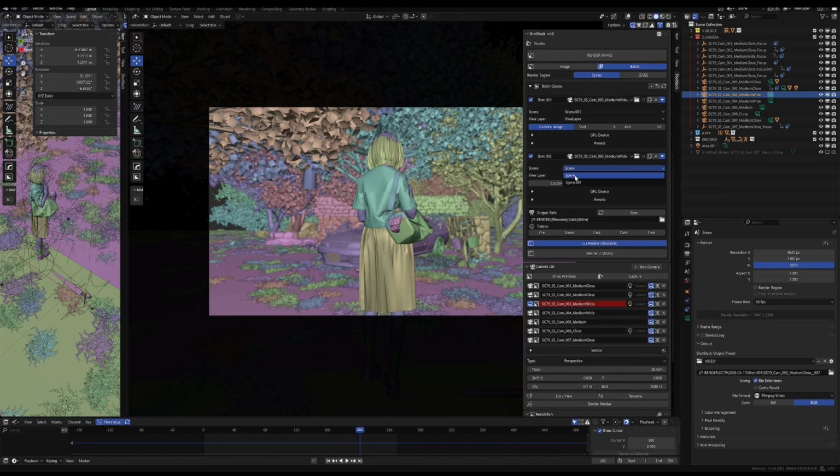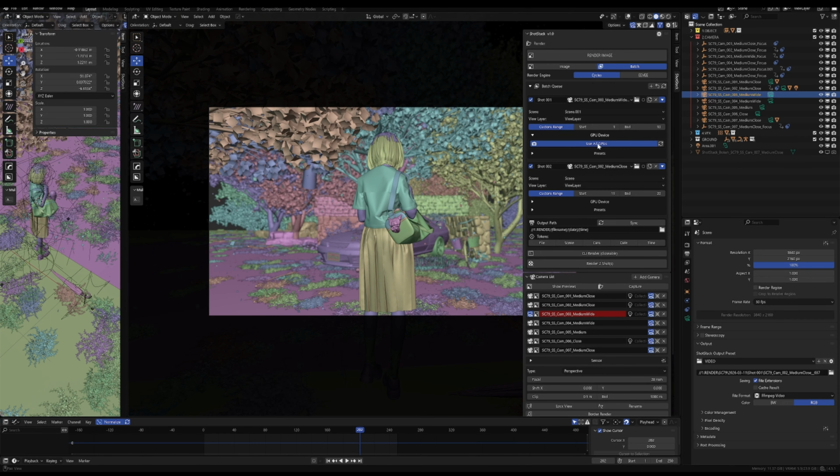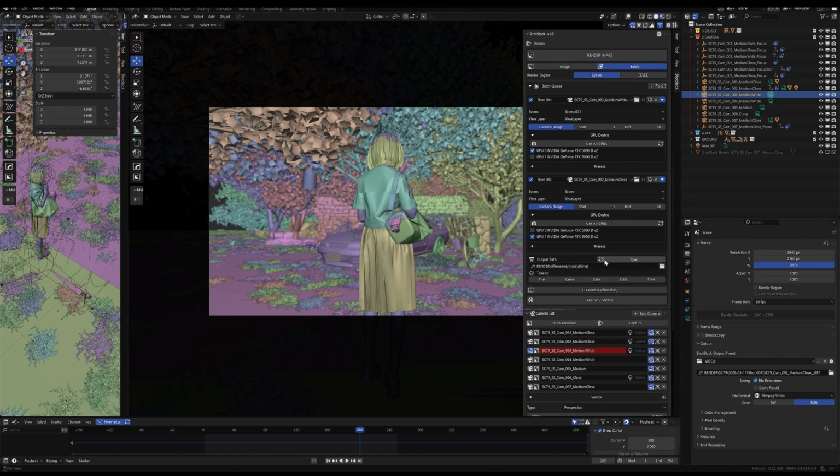in the Pro version, you can also manually select distributed GPU rendering for all your complex projects. First, let's open the GPU device settings. You can choose to use all GPUs by default, or manually specify which GPU to use. With distributed rendering like this, you might be aware of this information. When you use multiple GPUs for rendering, if you use all GPUs at once, then in Blender, the graphics cards may experience some performance loss.